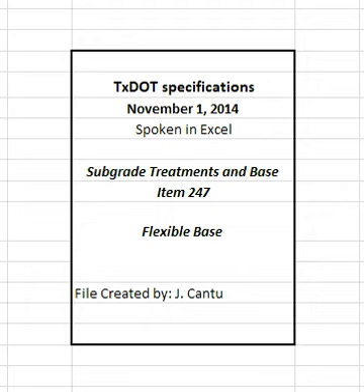Load by making successive vertical cuts through the entire depth of the stockpile. Do not add or remove material from temporary stockpiles that require sampling and testing before delivery unless otherwise approved. Charges for additional sampling and testing required as a result of adding or removing material will be deducted from the contractor's estimates. Haul approved flexible base in clean trucks. Deliver the required quantity to each 100 feet station or designated stockpile site as shown on the plans. Prepare stockpile sites as directed.